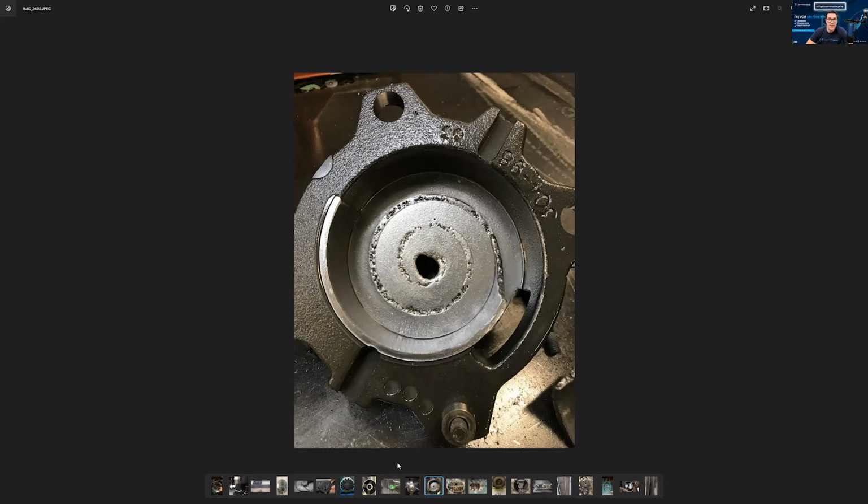And like Bob said, you have that scroll galling, that causes efficiency losses. So anytime you have flooded starts and you get those grooves in there, there's gas bypassing each one of those flanks, and so now you're losing efficiency. The compressor's still running, but it's not as efficient as it was.